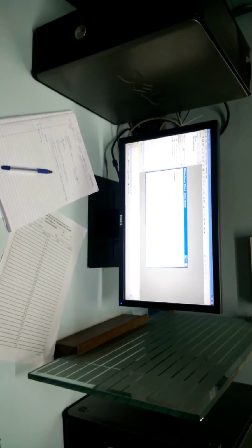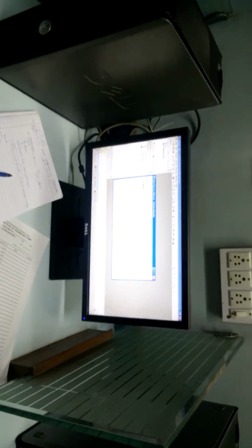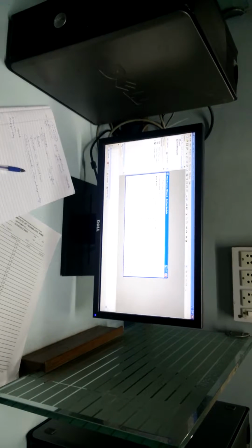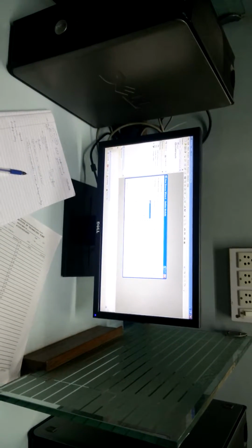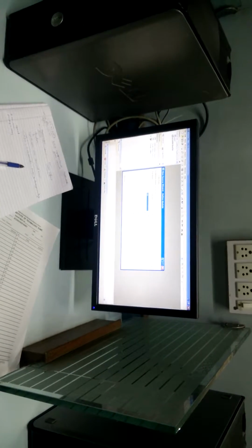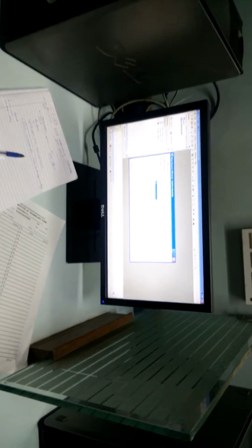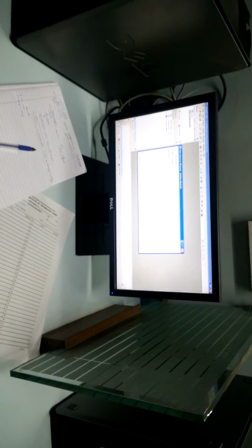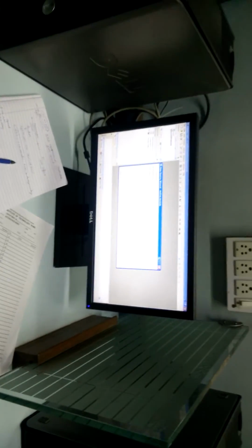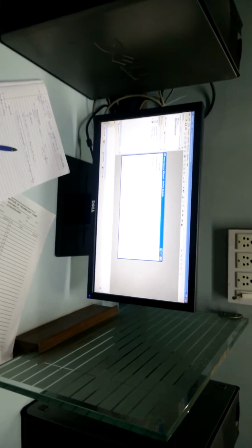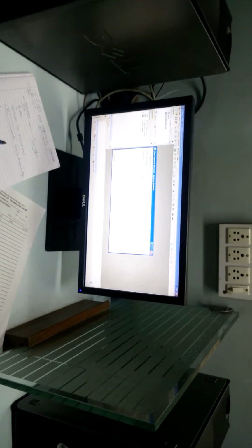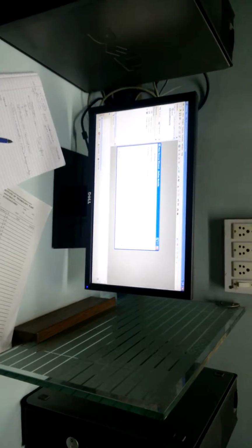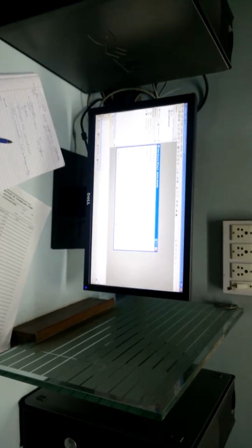Next, I will give inputs A, B and Y as the output. Accordingly, I will set the mode to in and out. If I want to operate on vectors, I will select bus, and accordingly I can set the values, whether I want 8-bit or 4-bit. Right now I want to work on scalar quantities, so input as scalar. I won't be keeping any bus part active. Okay. Next.